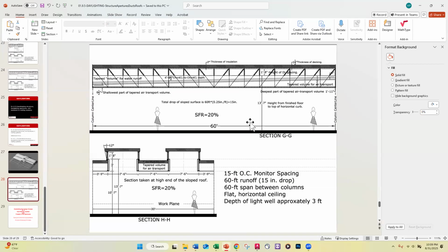But for right now, just to kind of get us started on this and not get totally bogged down in some of these details, we're just going to represent that ceiling with this 1/2 inch piece of sheetrock. And we all understand in the end that ceiling is going to be a little different. And whatever it is, it might tend to interfere with some of this airflow, in which case we may need to increase the height of the truss to accommodate whatever the depth of that ceiling structure turns out to be.